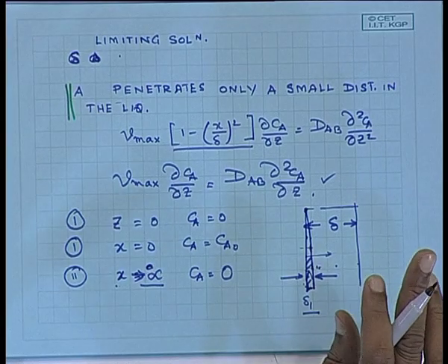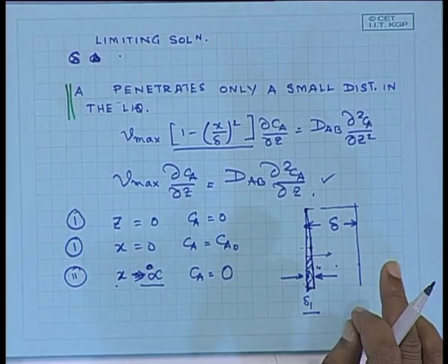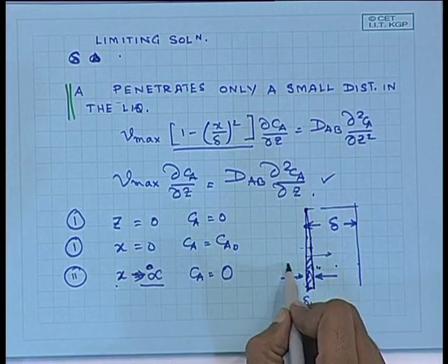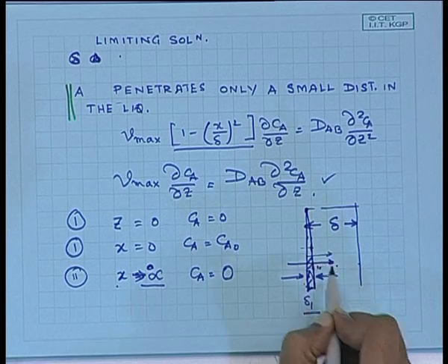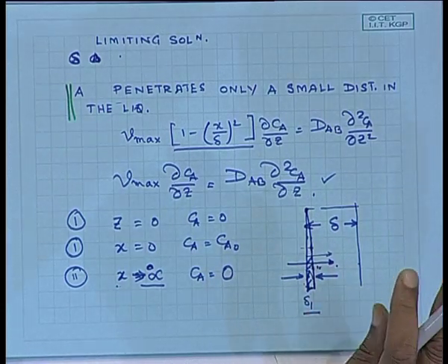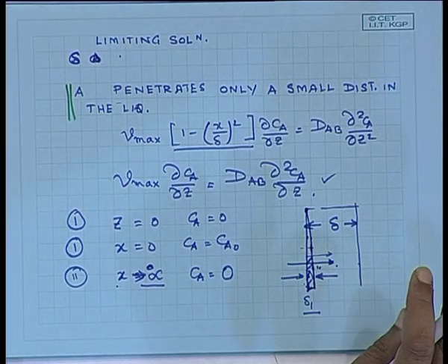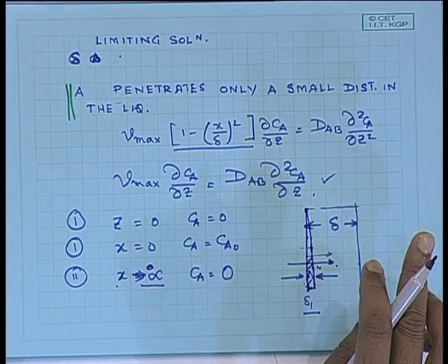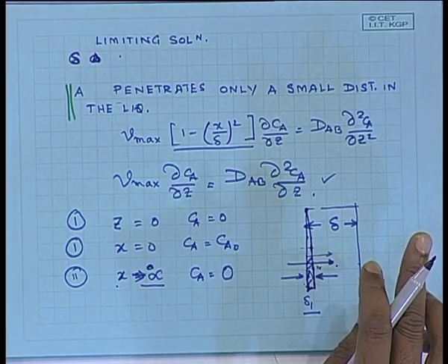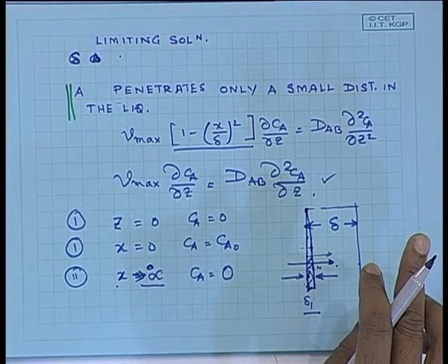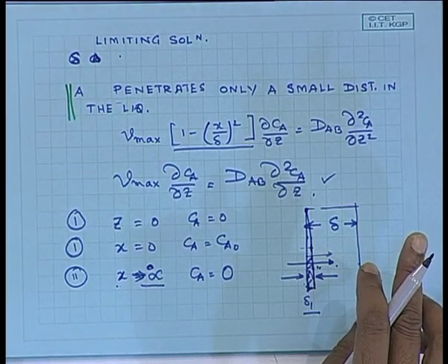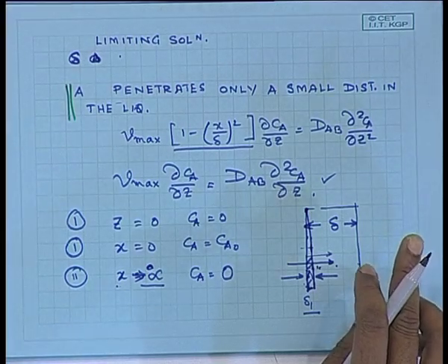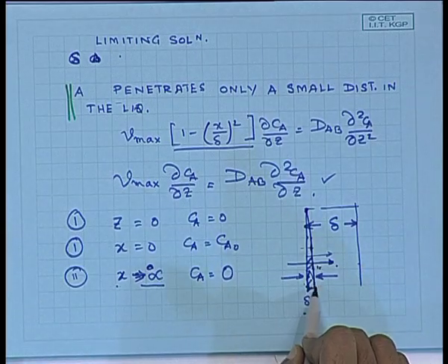If the viscosity is high, what is going to happen to the diffusing molecules? Would it be easy to move in this direction or difficult? If you put your finger across a falling film of water and a falling film of molten soap, obviously it is going to be difficult for the molten soap. So if it is viscous, then definitely you are going to have less thickness.